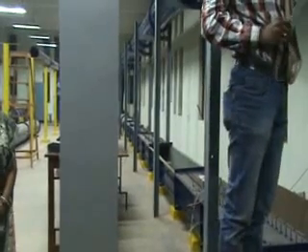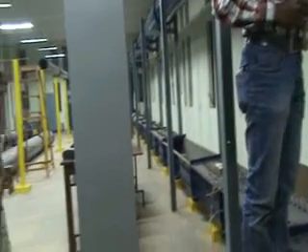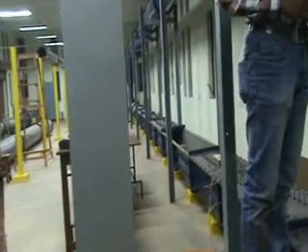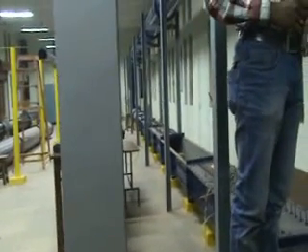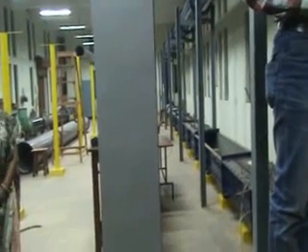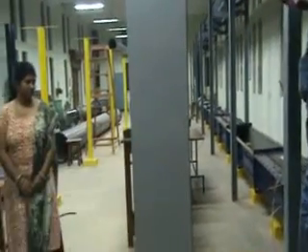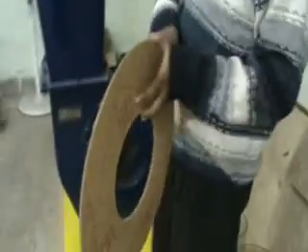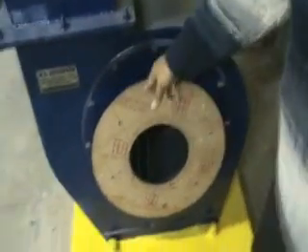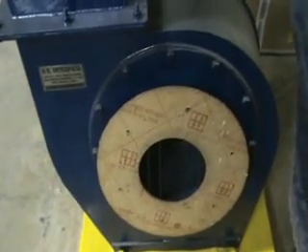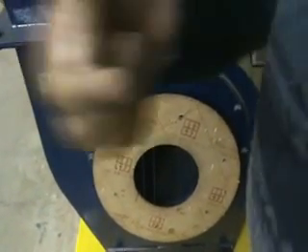So let us get another experimental condition. We will put a throttling device to change the quantity, and accordingly we can also note the pressure drop across the orifice plate. Let us create another experimental condition. Now this is a throttling device. We are putting it here to control the flow. Once you put this, the flow control will change, so our experimental condition will change.